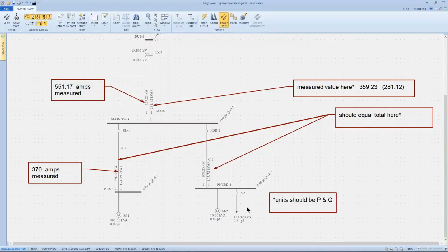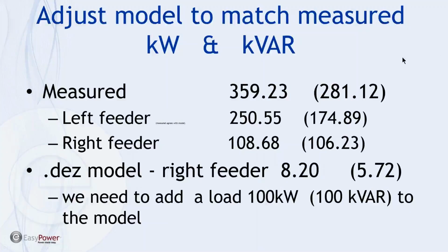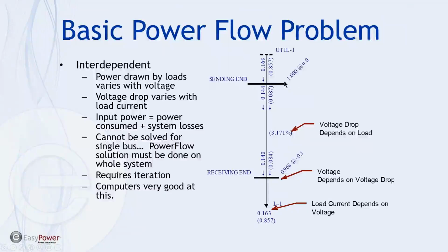First of all, we want to know why this much difference exists. If we're aware that there are some loads that we didn't factor into the short circuit study, that's one solution. But as far as the benefit of PowerFlow results over time, the more accurate these are, the better off we can be. Now, if you jump back into EasyPower, back into my slideshow, that's a technique of balancing the loads.